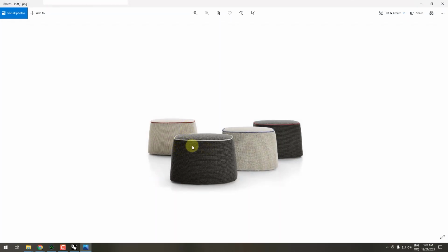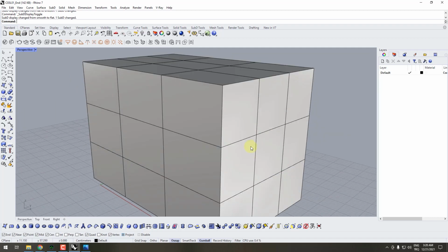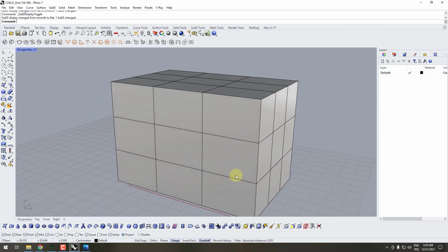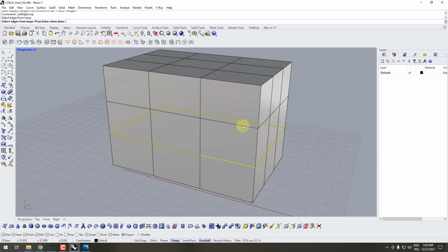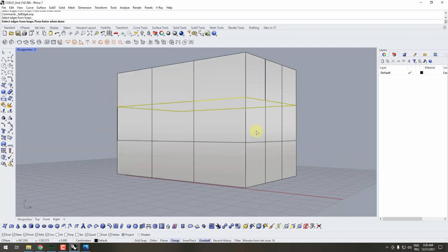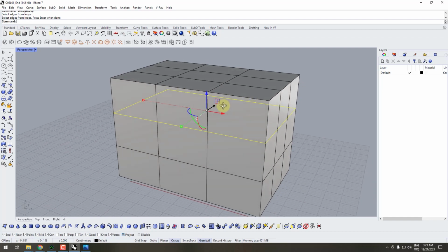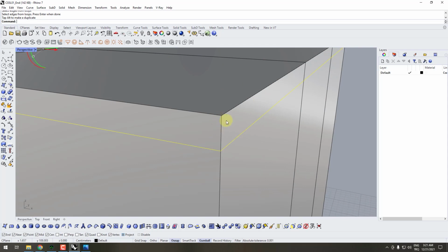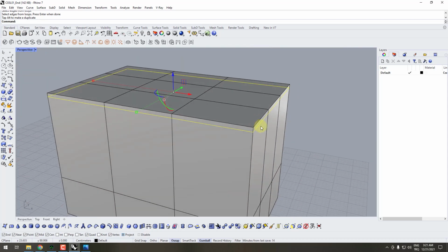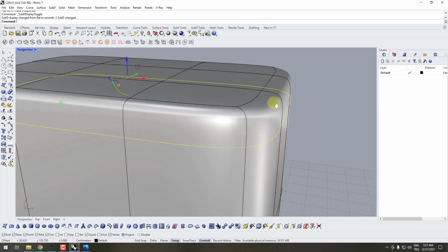To keep the smoothings to a minimal, I need to squeeze these rounding edges with other edges. And now we have these sections, these edge loops here. So I can use the select loop command, and for example I can select the upper edge loop in the middle, and then using gumball I can push these edges in near position to the top edge, and by doing this I can accomplish a more tight rounding on the upper side.